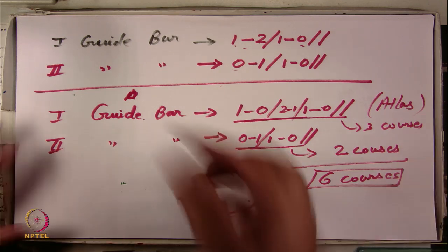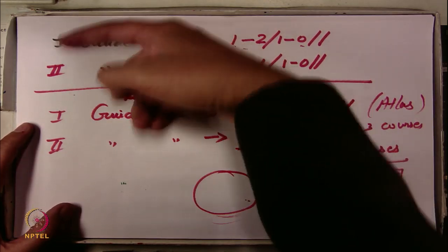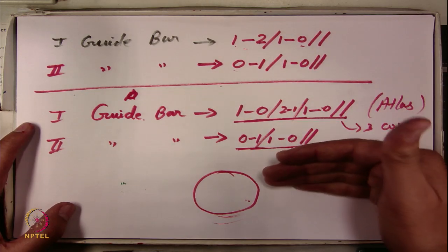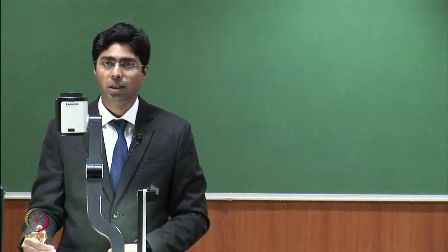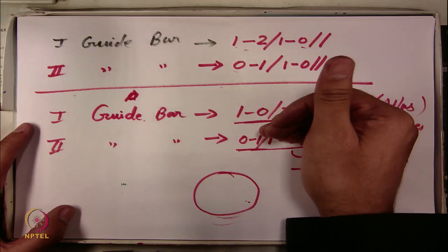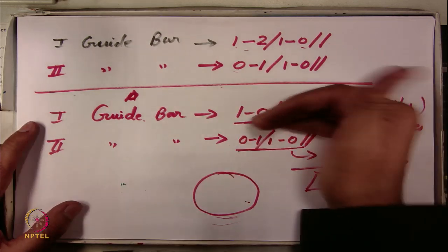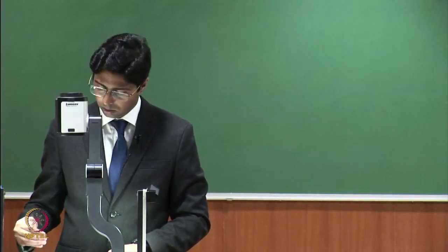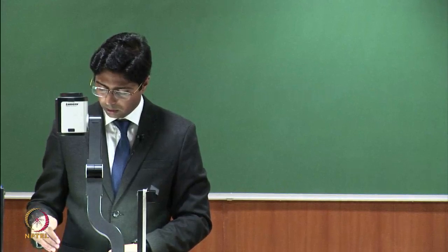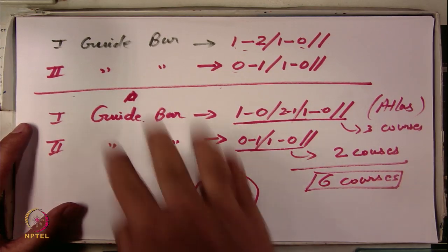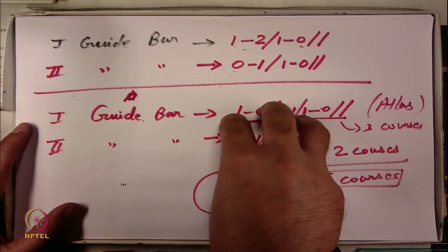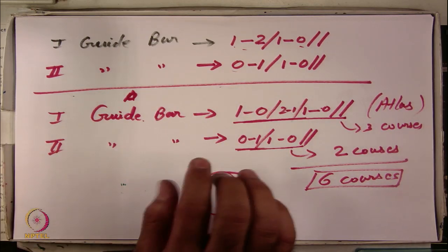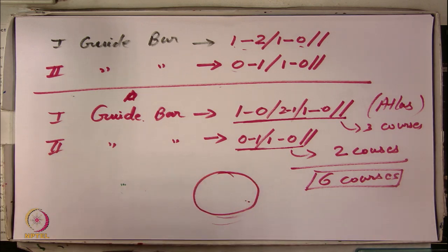In multi-bar constructions, when you have different types of guide bars like 1 to 8 guide bars, you can see how the designs can keep on getting complicated. But the principle remains the same. First step, you need to put the links in a sequence for one guide bar. Similarly, you need to put the sequence of the second guide bar. If the repeat course is different, then you have to make sure that the pattern drum revolutions complete the repeat designs for each guide bar. Okay. So, this is how the chain links for double bar constructions are made.